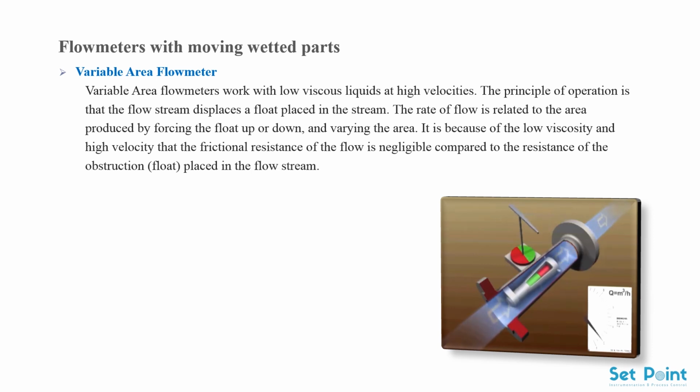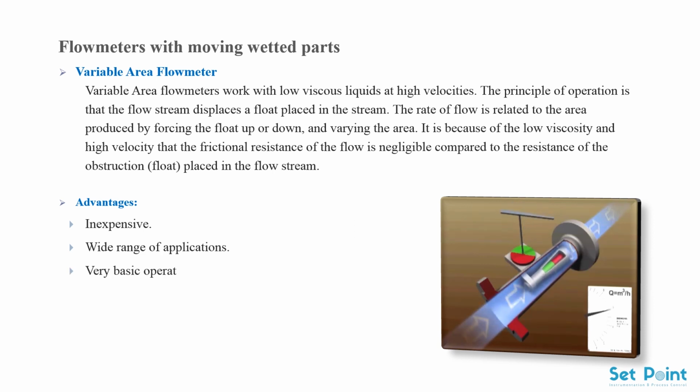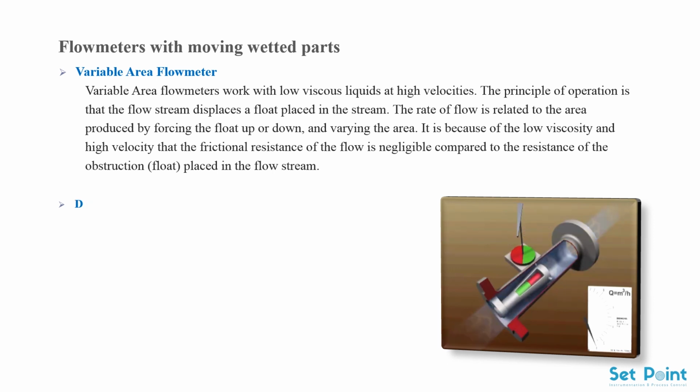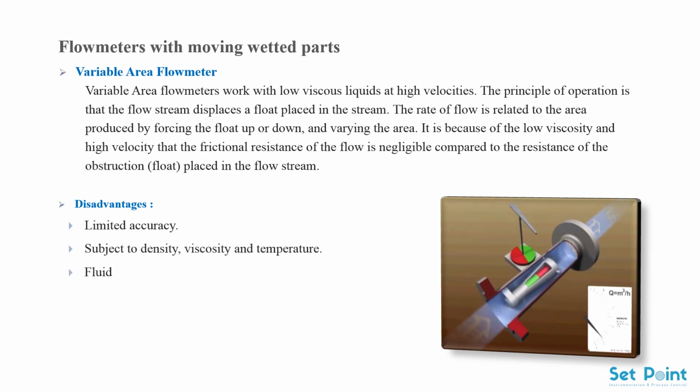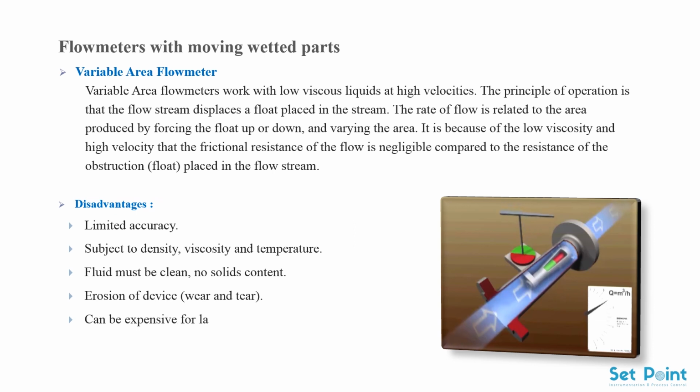Advantages. Inexpensive. Wide range of applications. Very basic operation. Easy installation and simple to replace. Disadvantages. Limited accuracy. Subject to density, viscosity, and temperature. Fluid must be clean, no solids content. Erosion of device, wear and tear. Can be expensive for large diameters. Operate in vertical position only.